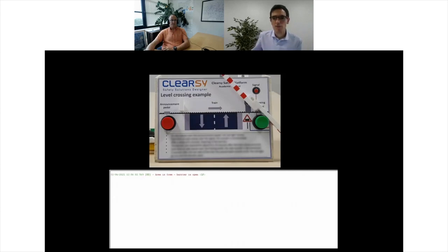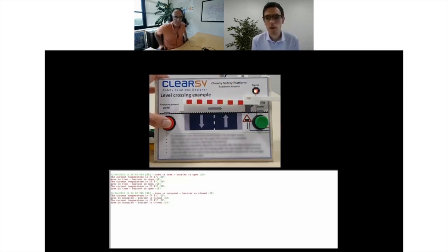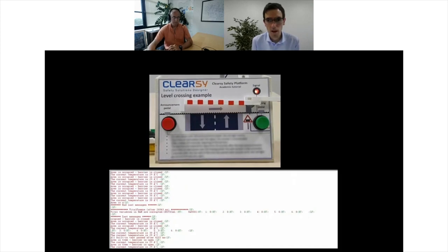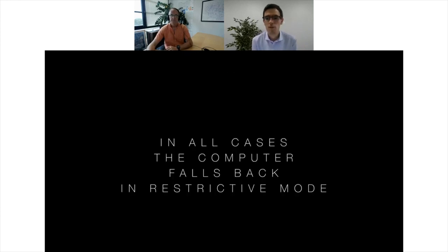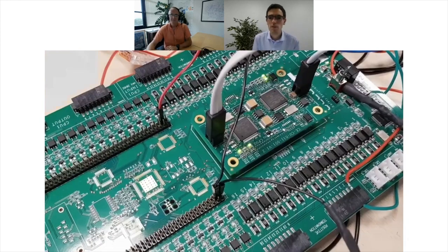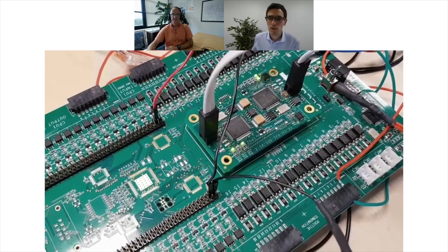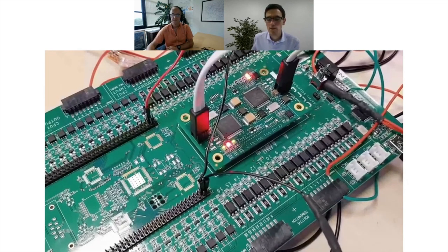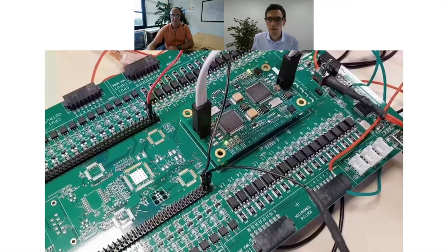And for the systematic design failure, we will press the entering button, the announcement pedal, 9 times. And here you have an error, and you can see that even if we press the button for freeing the area 9 times, the barrier remains closed. In case of failure, in case of shutdown, the red LED lights up.